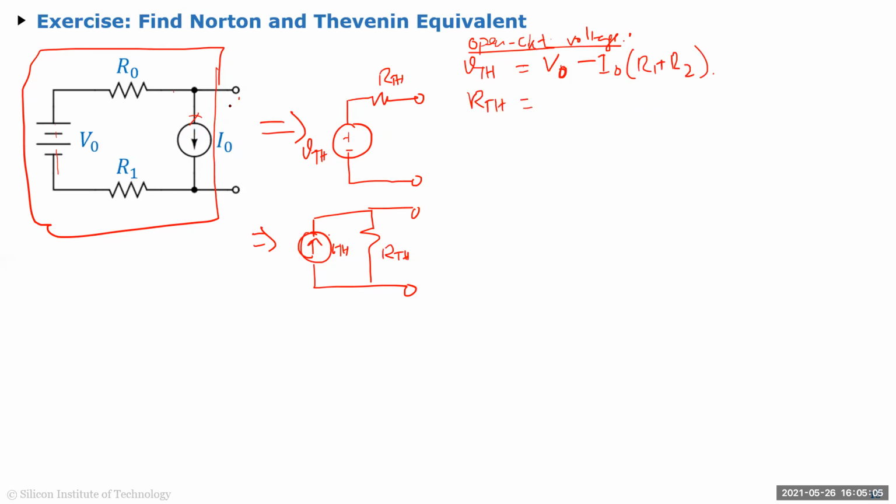obviously you find the resistance. There is no capacitance or inductor, so we just find the resistance. So you make all the independent sources zero. So you open current sources, short voltage sources, and then this is R1 plus R2, right? So I think that one everyone got, R1, R2. All right, so that's your Thevenin equivalent. And if you want to be really lazy or cheat, you could have made your RTH as this, right? Or don't cheat, but at least to cross check.